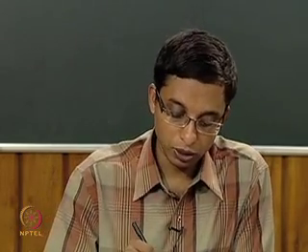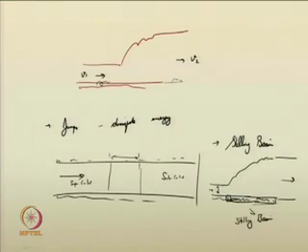So, a stilling basin is a particular location in the channel reach where the jumps are provided, and we can design it like that. You can use stilling basins for dissipating energy; stilling basins will create hydraulic jumps that can dissipate the energy.